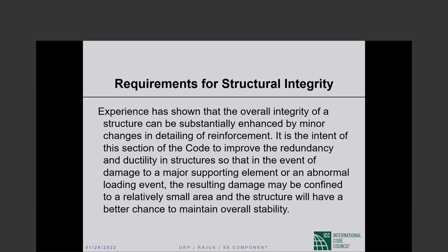if it is seismic design category D, it is special moment frame joint, then I will give you all the details in either next week or the week after. I don't know, it's coming up. If it is not a special moment frame, then there are hardly any requirements until ACI 318-19. So all you do is provide shear reinforcement, any shear reinforcement that might be needed. So there are really no specific details given for ordinary or intermediate moment frame joints. Special moment frame joints, there are details, very specific details that I will share with you in the next couple of weeks.